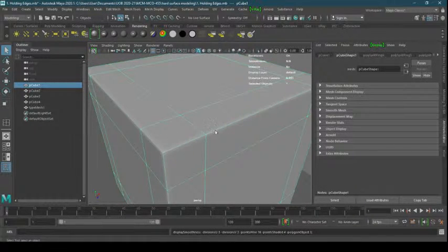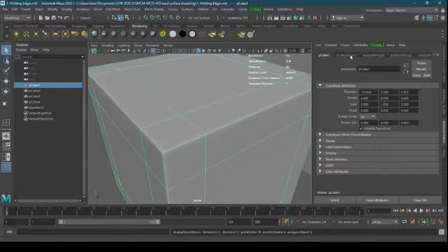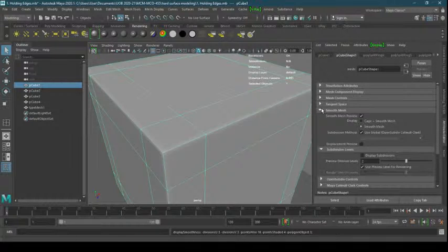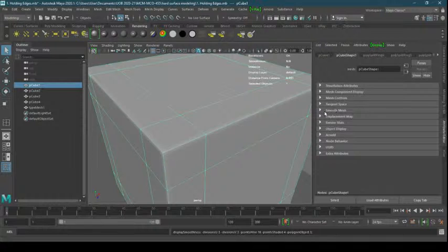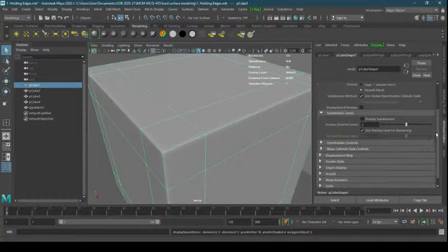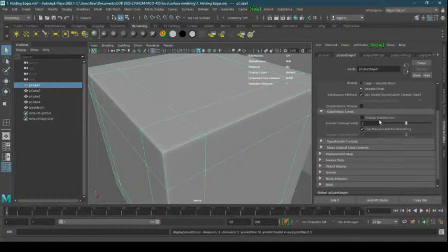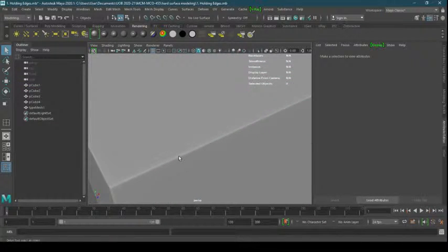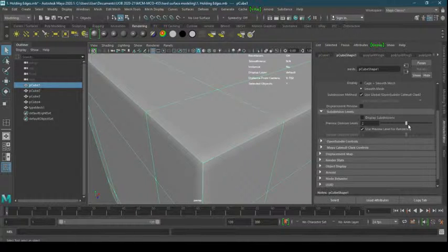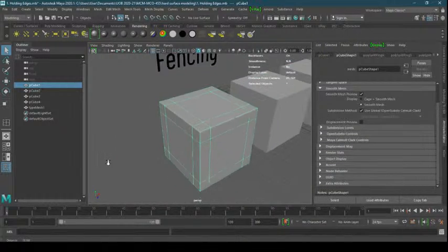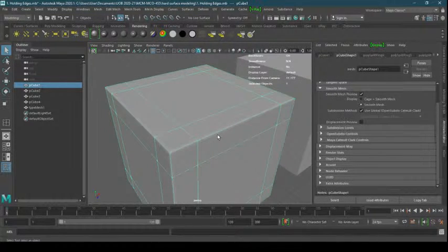So when you press 3, you get this option. And if you think the smooth modifier that you apply by pressing 3 is not strong, what you can do is go to your options here, and in the pCube shape, find Smooth Mesh Preview, and right now it's number 2. I can increase it more, so you can see the quality is getting better and better. At 3 it looks much better. You can do that, but I always keep it at 2. Okay, so is this part clear?